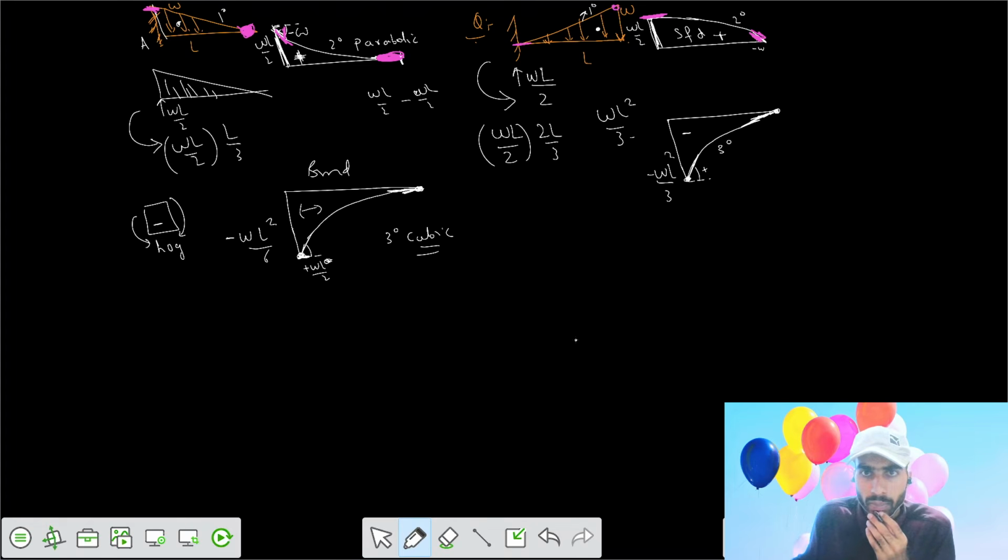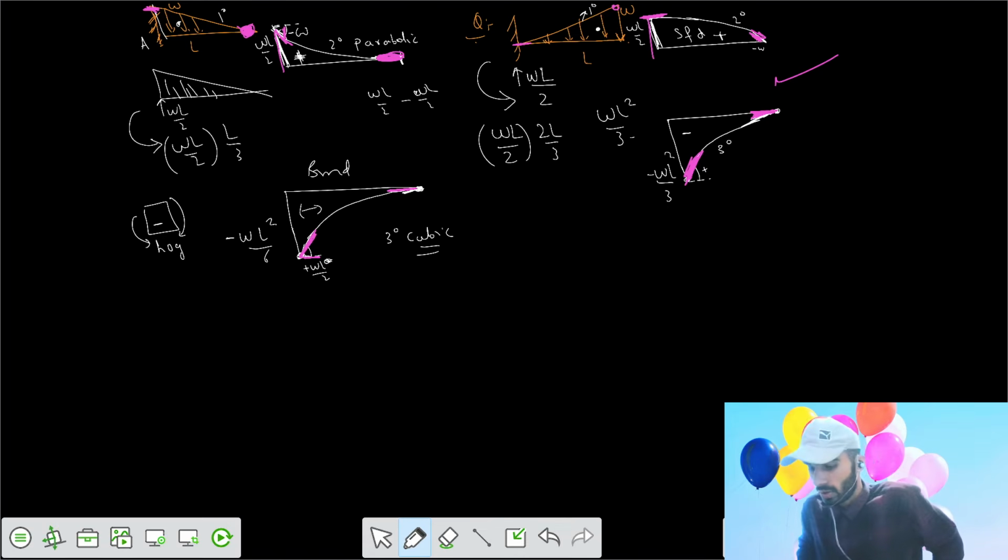And for the bending moment diagram, you are having a slope equal to WL/2. But here the shear force, the slope is 0. Yeah, it's correct. Now coming back to this part, see, the shear force here is WL/2. That means there has to be a slope of WL/2 here, positive, and the shear force here is 0. So okay, everything is okay. I thought there was some mistake.